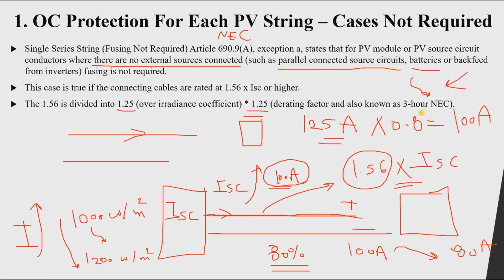Now another thing that you will find, these rules that I'm talking about in this slide, similar in the IEC code. So in the IEC you will find it is similar to the NEC. Same rules. If you have a single string, you don't add any fuse. Okay.